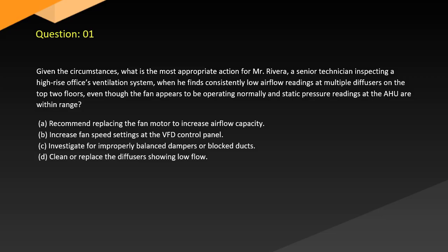Recommend replacing the fan motor to increase airflow capacity. B. Increase fan speed settings at the VFD control panel. C. Investigate for improperly balanced dampers or blocked ducts. D. Clean or replace the diffusers showing low flow.